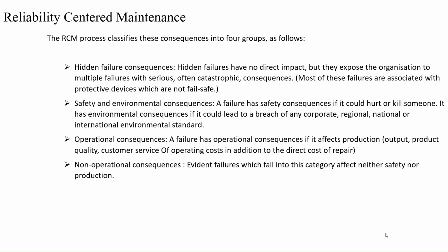Operational consequences. A failure has operational consequences if it affects production, output, product quality, customer service or operating costs, in addition to the direct cost of repair. Non-operational consequences. Evident failures which fall into this category affect neither safety nor production.